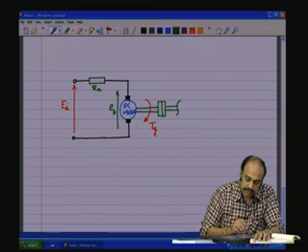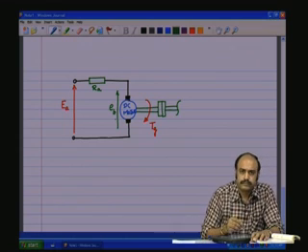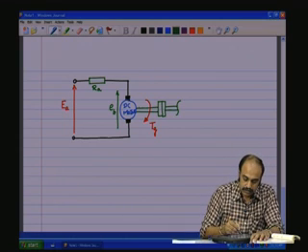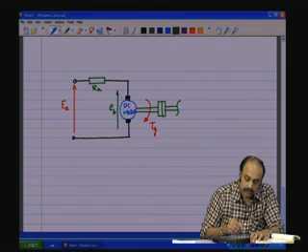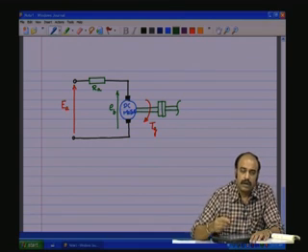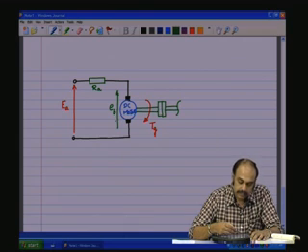Though the applied primary voltage has caused the rotation, this rotation of the shaft is going to cause currents to flow through the windings of the armature and produce an EMF across the brushes, along the same principles that we discussed for the DC generator. Now, this EMF will always be produced irrespective of what causes the rotation of the shaft,